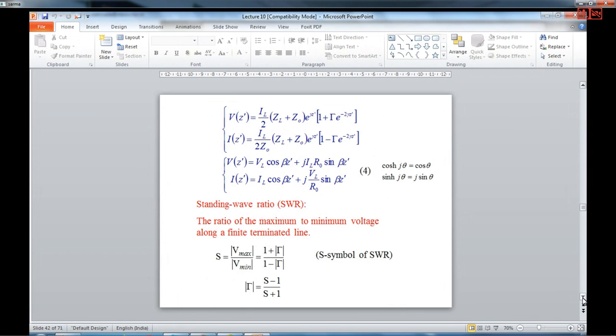Particularly in good olden days, people wanted to measure and see how good the reflection is there or a bad situation or what is what. So thereby they wanted to introduce a new parameter called standing wave ratio, which is easily measurable, which is measured at various locations along a transmission line, giving you the same values, or expected to give the same values. And so if you measure at various locations, take an average, your measurement error is very, very less. So these are all the advantages with the standing wave ratio.